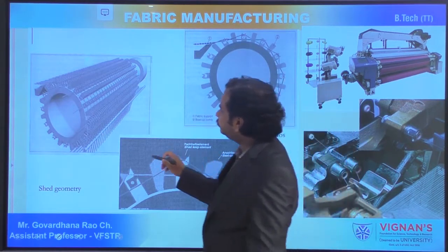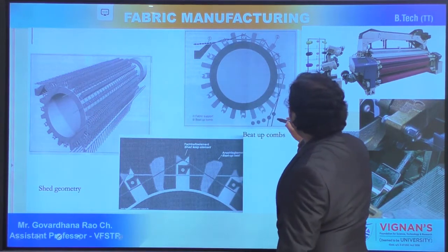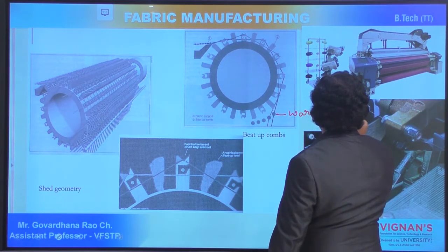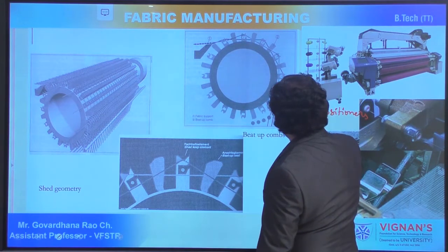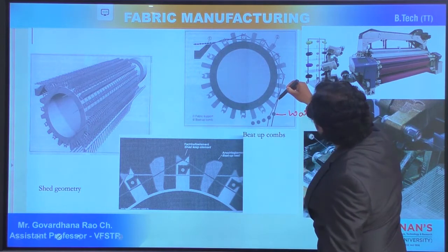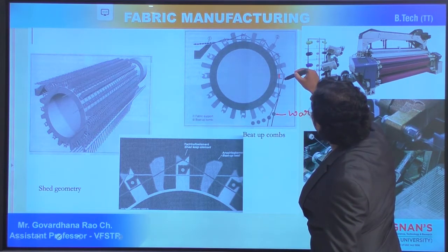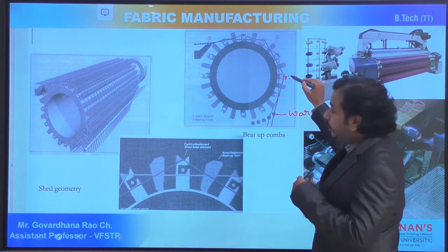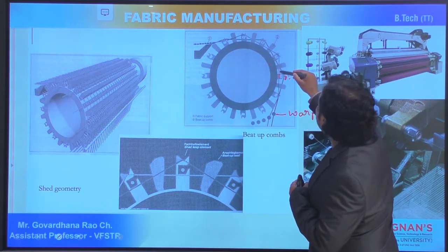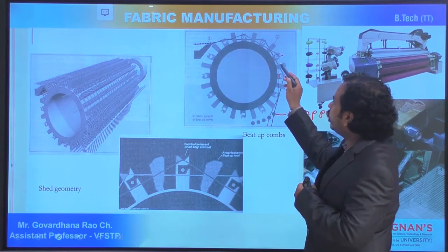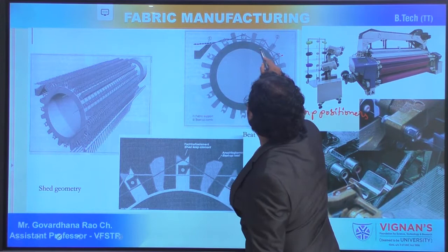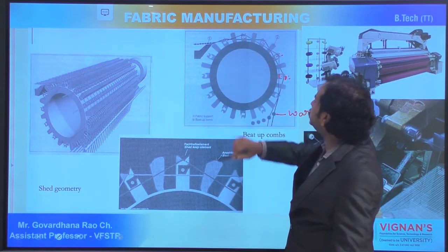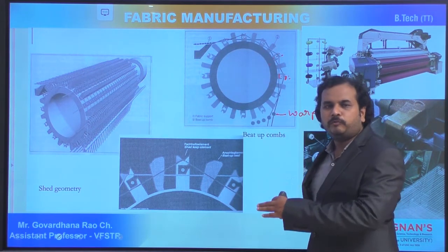So you can observe that this is the complete drum, and you can see the warp positioners. So these are the warp positioners. Okay. And you can see that these warp threads, you can observe this thread is going down to form the lower shed, and this thread has gone above, falling on the top of the shed forming element to form the top shed. Now this yarn falls down to the lower shed, this will be on the top shed. So one by one. Now with the help of these beat up elements after the weft insertion, you can understand here the dots indicated 1, 2, 3 and 4 picks are there. So 4 positions, 4 sheds are formed, 4 picks are inserted.